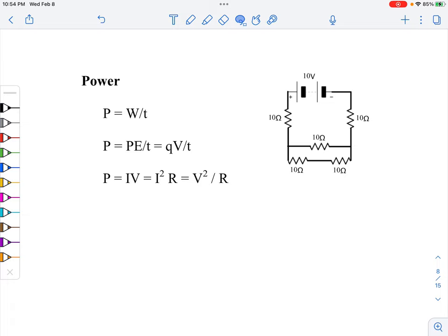The downside, aluminum has more resistance than copper. If there's more resistance, that means when you transmit, for the same current, more of that power is going to get wasted as heat. We don't want that. We're going to minimize that. That's energy loss. I'm not stringing wires through the air to heat the air up. I'm trying to send electrical energy.